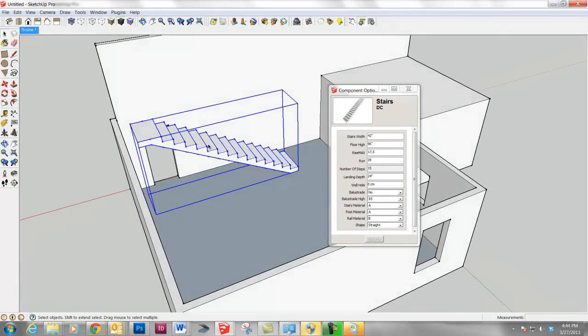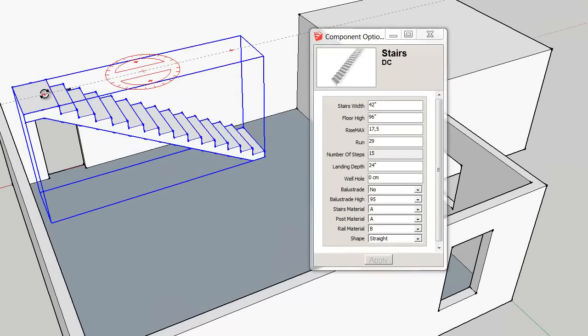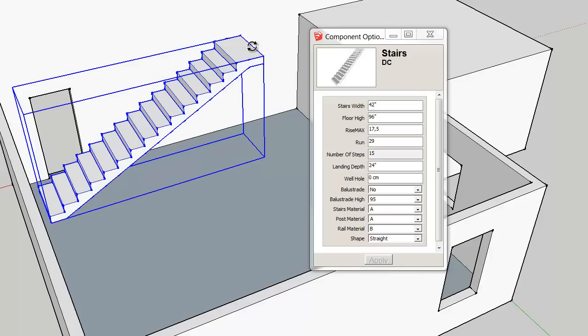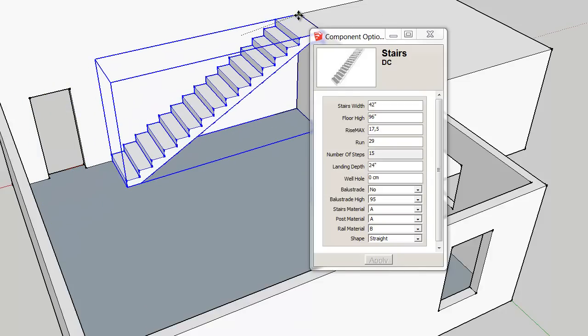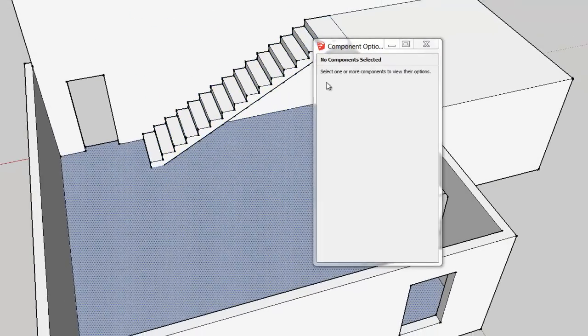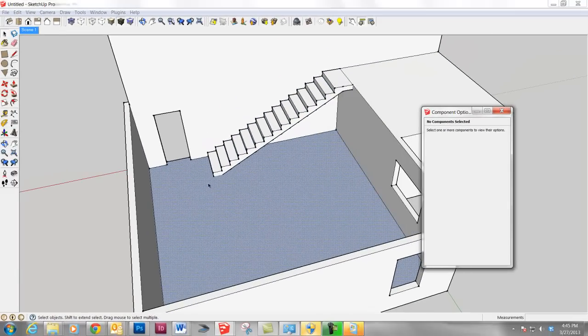And we need to turn it around. Again, the quickest way to turn something around is just hit M for the move tool and then hover over the 4 little red dots, and you're going to get instantly moved to the rotate tool. Let's rotate that around until it snaps to 180 degrees, and then let's go ahead and move it until we snap on the corner. So let's go ahead and move this box over.